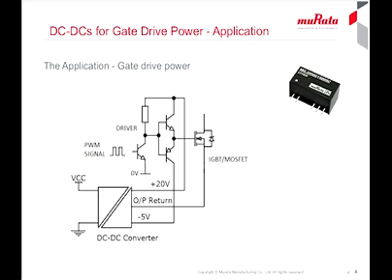The switch needs to be controlled by pulse width modulated, or PWM, on-off signals to its gate, and with large devices, significant power is needed to do this because of the high gate charge of these types of power switches. The on and off drive voltages are critical for best efficiency and low EMI, so the gate drive circuit has to be carefully designed and powered correctly. This is where the DC-DC converter comes in.